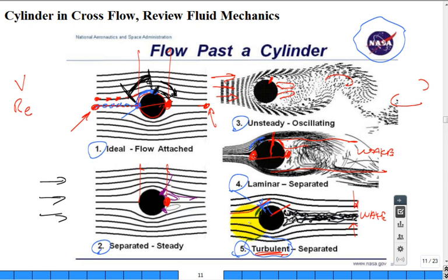Why do we have dimpling on golf balls? Same thing. The dimpling helps trip the flow and make it turbulent so that it makes the wake region in the back smaller, less of a pressure drop, and the ball goes further for the same hit.